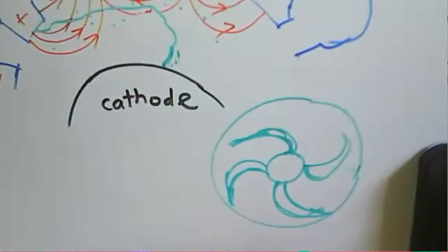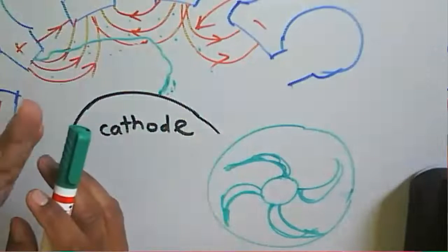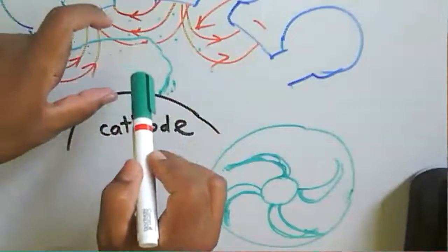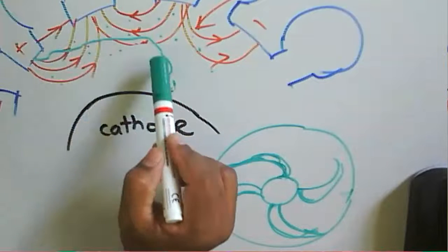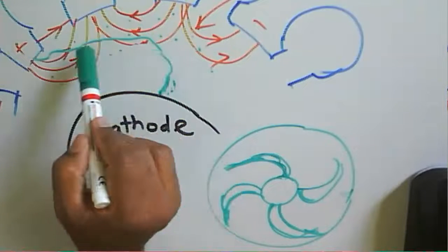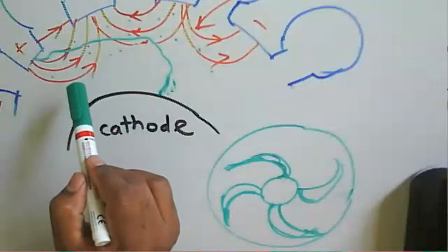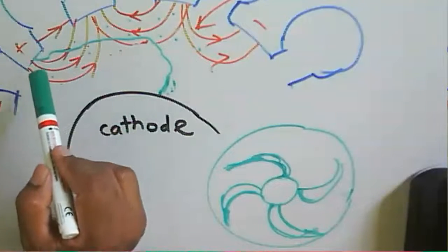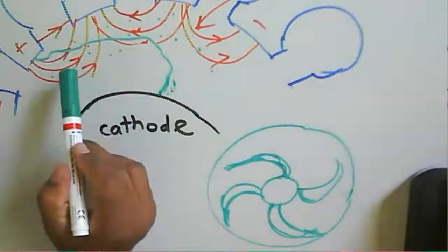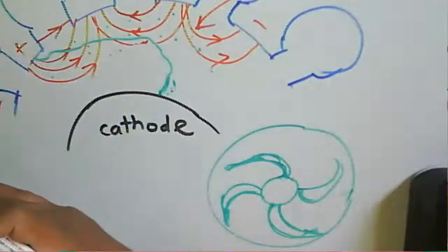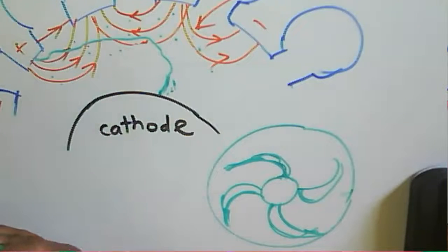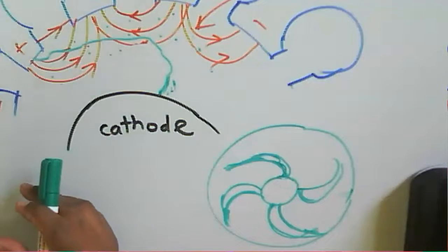But the electrons interact in this magnetic field region with this alternating RF field, and because of that the electron will move faster or slower. So the path of the electron will be bent by the magnetic field as well as by the electric field. If the electrons interact in the positive cycle or the negative cycle, they will be accelerated or decelerated accordingly. So the same thing, velocity modulation takes place here.